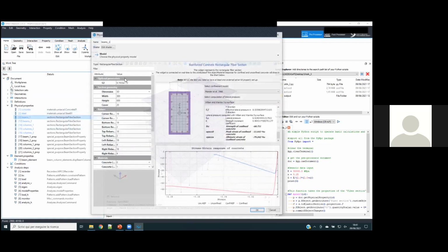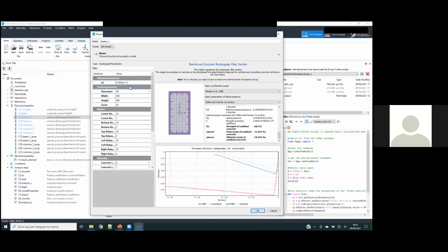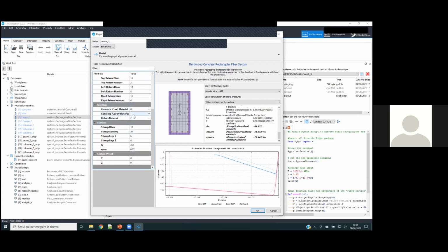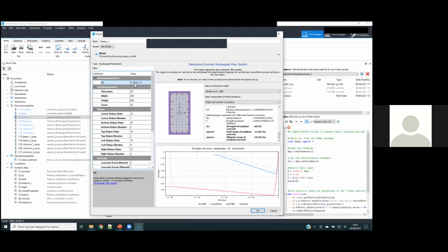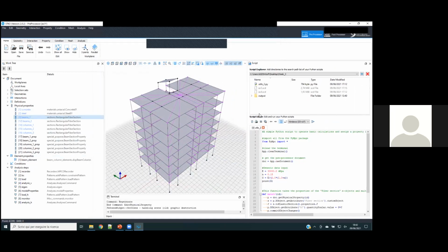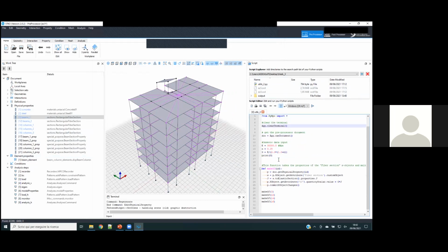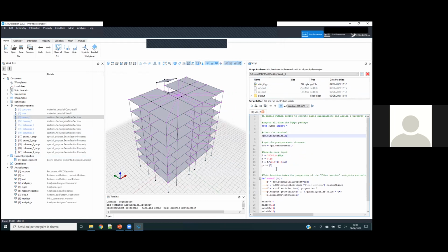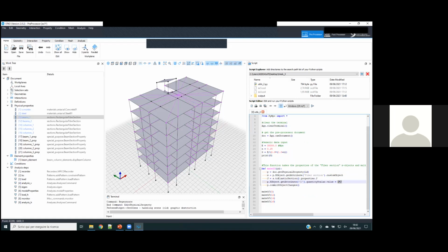We created rectangular fiber sections by defining corner rebars and all the rebars, all the materials. And we had to define this GJ parameter for everything. Now in OpenSees, it's obligatory to input it. To do that, we use this very quick script that you will also receive. It's the same as the one I shared with you last week of the course. We're just defining Young's modulus, calculating the shear modulus from it, and then casting, let's say, transforming the fiber section into an elastic section to extract our inertia and making the operation inside of it, assigning this property to the appropriate metadata. So this is our metadata that we want to assign to GJ.